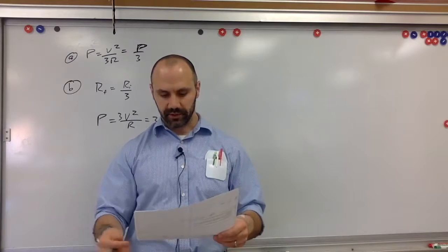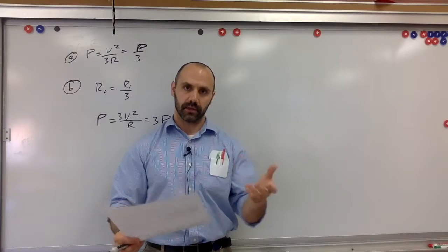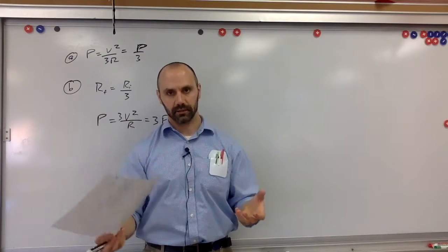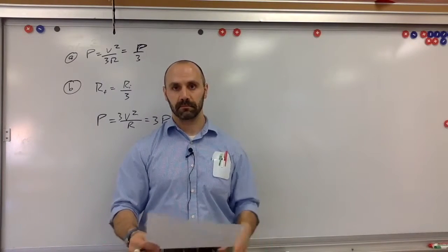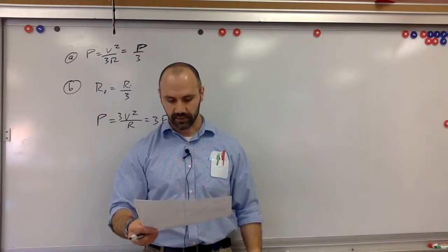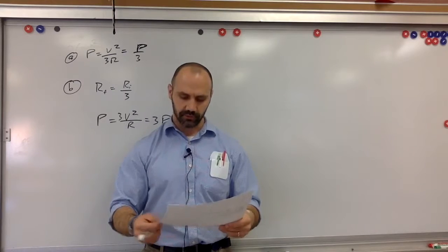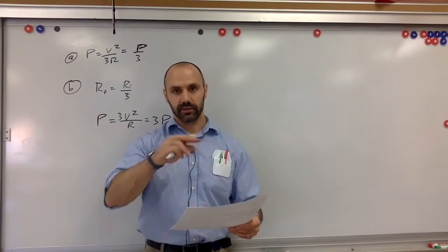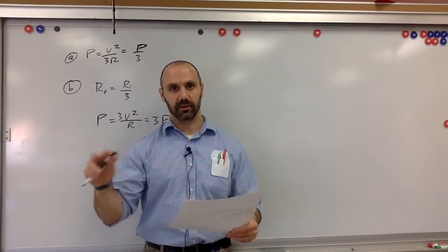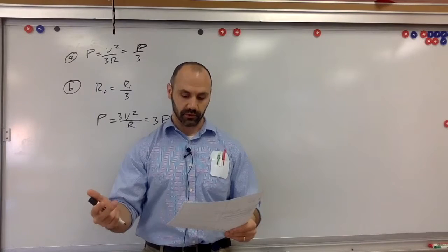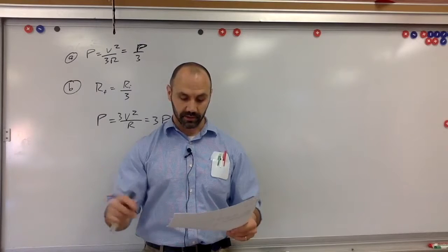Okay, household applications, we've got kilowatt hours. A kilowatt is power, and you're multiplying it by a time unit, hours. So kilowatt hours is actually an energy unit. It's how much energy has been used, and that's what shows up on energy bills and that kind of thing. And from chemistry or maybe physics last year, the change in thermal energy in terms of heat is mc delta T, and that's the energy, so that's power times time, so that's V squared over R times the amount of time that power is being used, and that'll tell you how much something is heated up.